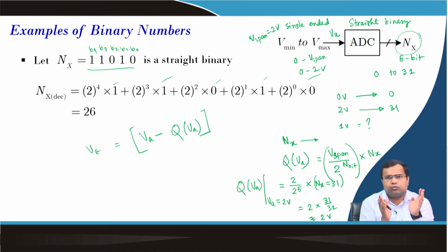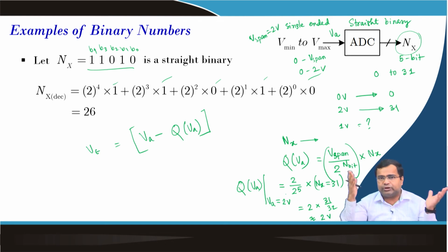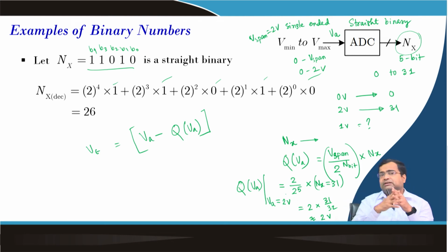So, the processor width will also be smaller, because if you deal with 5-bit data, then all the controller and filtering operations will be dealing with 5-bit input data. But imagine if it is 10-bit data, then you have to do all the arithmetic operations with 10 bits. So naturally the size of the hardware architecture will increase, power consumption will increase, the propagation delay will increase, but the resolution will improve. That means it is a trade-off between the accuracy and the power consumption or your computational time.